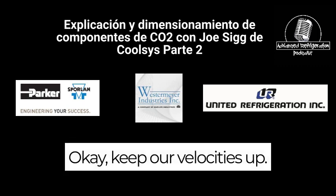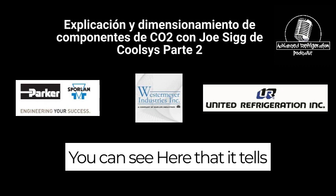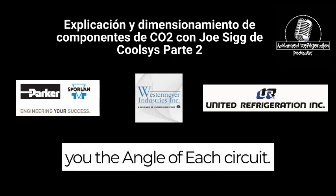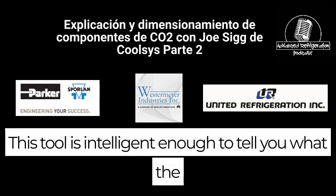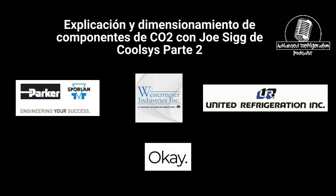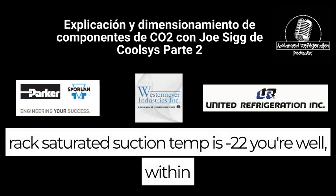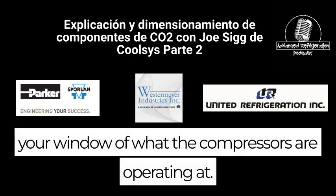So we keep our velocities up and our pressure drop low. You can see it tells you at the end of each circuit. This tool is intelligent enough to tell you what the saturated suction temp required will be for that circuit. Your rack saturated suction temp is -22, so you're well within the window of what the compressors are operating at.